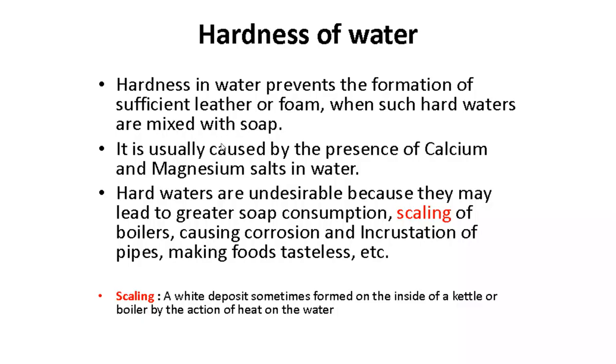Hardness in water prevents the formation of sufficient lather or foam when such hard waters are mixed with soap. It is usually caused by the presence of calcium and magnesium salts in water. Hard waters are undesirable because they may lead to greater soap consumption, scaling of boilers, causing corrosion and incrustation of pipes, making foods tasteless, and other drawbacks of this hardness.